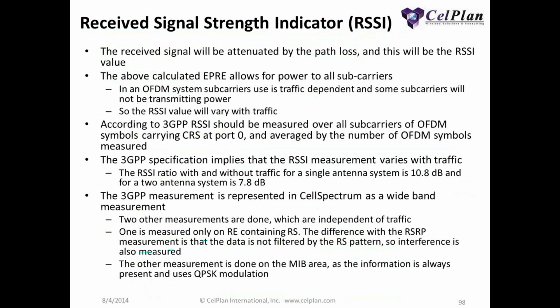So what is the issue then with the RSSI? It is that the RSSI will vary with traffic. Depending on the traffic, you will see a different value of RSSI. So it's a measurement that is really very critical, because if there is traffic, there is one measurement; if there is no traffic, the measurement is different. And the variation can be up to 10 dB for a one-antenna system, and up to 8 dB for a two-antenna system.